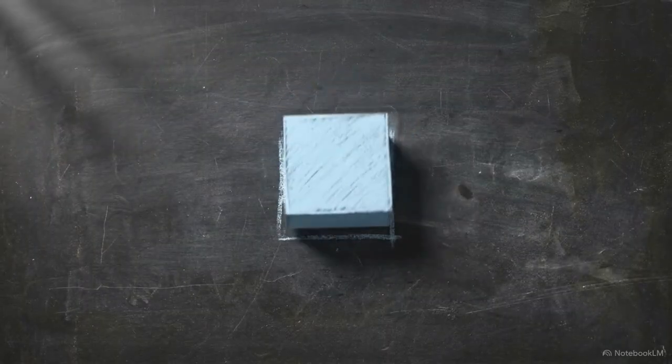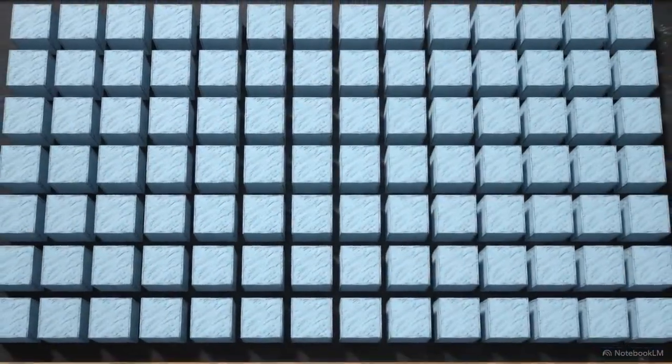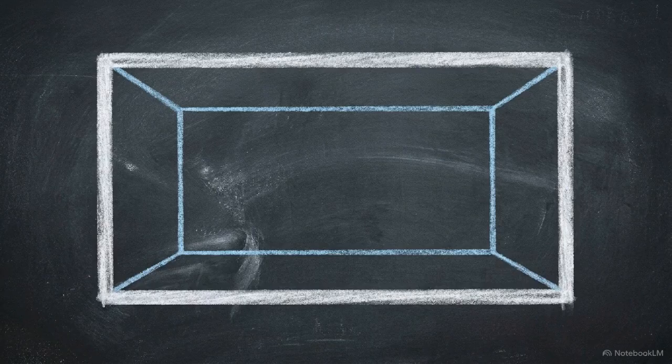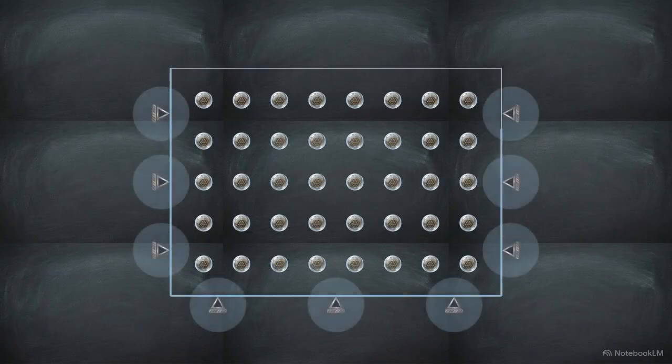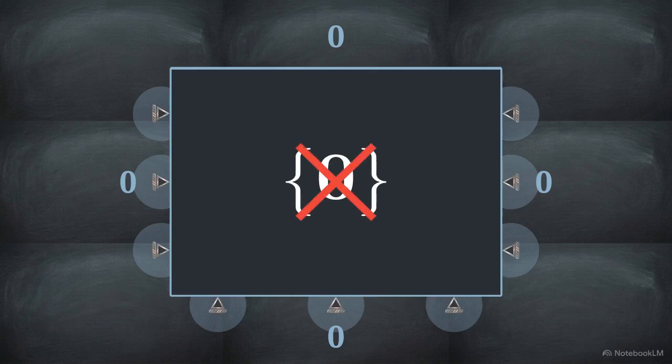Watch what happens as we take that single mathematical element and rapidly multiply it into a dense, sprawling continuum. The exact partitioning logic we just derived for a 4-node rectangle scales automatically to handle stiffness matrices containing thousands of elements. To prove this algorithm at scale, we use a standard computational benchmark known as the cavity flow problem. The parameters are strict. 3 outer boundaries of our domain are forced to absolute 0, while the top edge is held at a constant unit value of 1. If we skipped the matrix partitioning step, the 3 zero boundaries would dictate the entire system, pulling every calculation down to a trivial 0 vector.